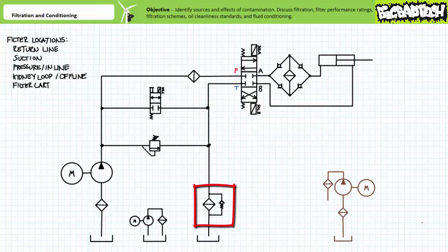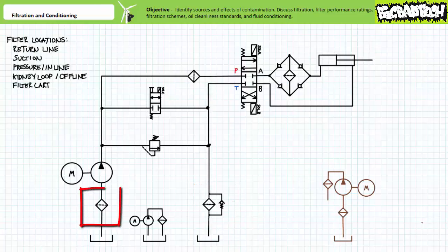Any fluid routed through the system must go through the return filter at low pressure prior to being emptied into the reservoir. The fluid in the reservoir is then allowed a chance to cool, settle out any remaining particles, and dissipate any entrained air before it is pumped back into the system. We'll examine reservoirs, a necessary component in hydraulic power units, in a later lecture. Return filters, as the name implies, filter oil returning to the tank. A suction filter, sometimes called an inlet or sump strainer, in contrast, filters oil prior to it being introduced into the system by the pump.